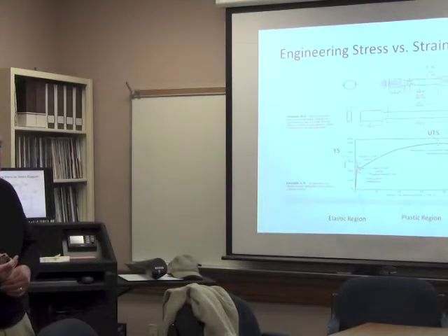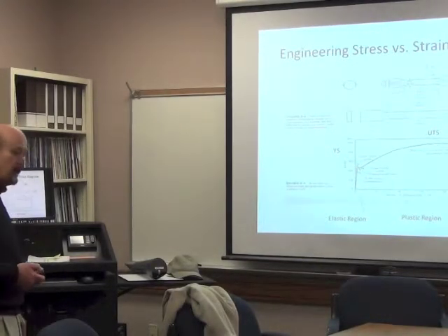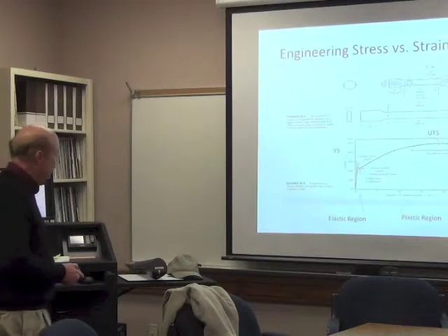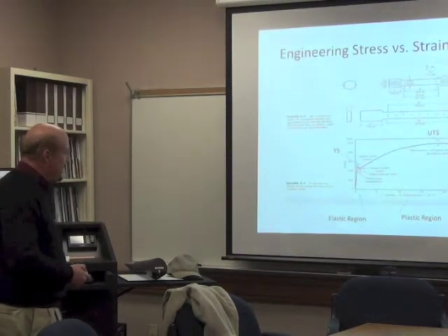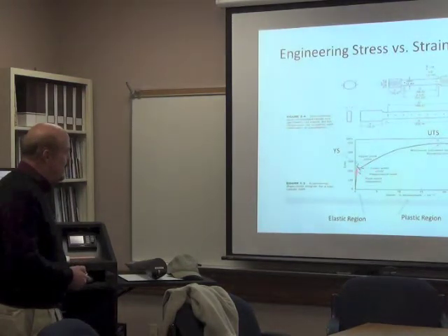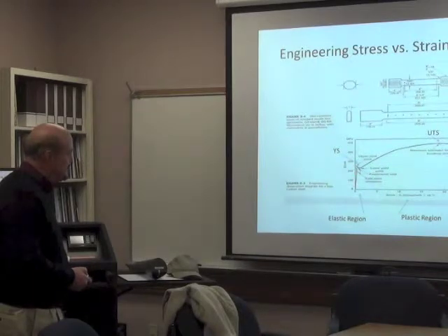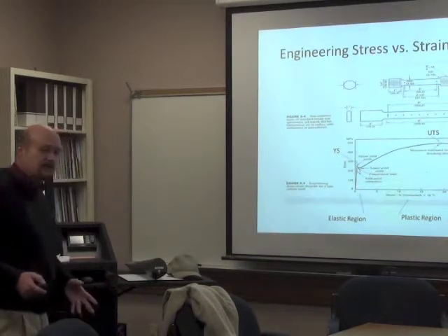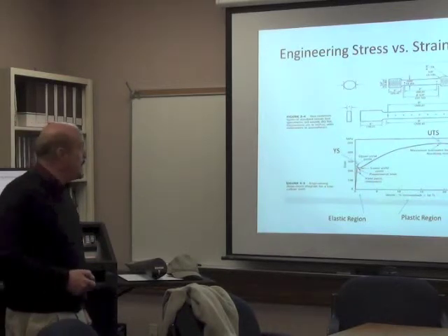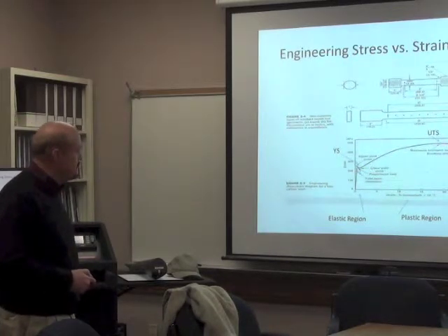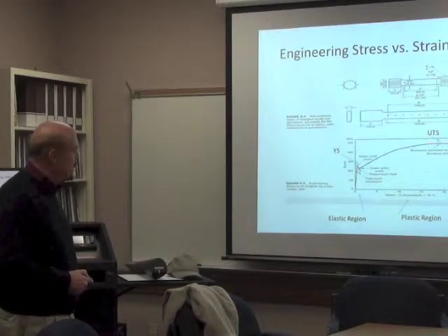Okay. Now, what is interesting is that all the different steels have the same straight line region, the same E value, like when you take the tangent of this angle, the stress over the strain. They all have the same modulus of elasticity. It's their ultimate tensile strength here, the UTS, the maximum ultimate load, that value there, that varies.